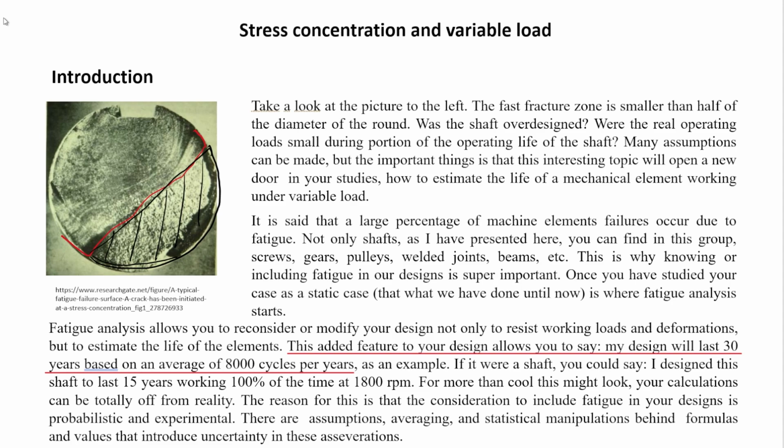However, let's remember something important: fatigue design is based on experiment. So it's not a strong analytical tool derived from the physics, but it is highly dependent on statistics and experiments. And reinforcing that, whatever statistical measures you apply, you need to be careful with them, because it's not a precise forecast about what's going to happen.